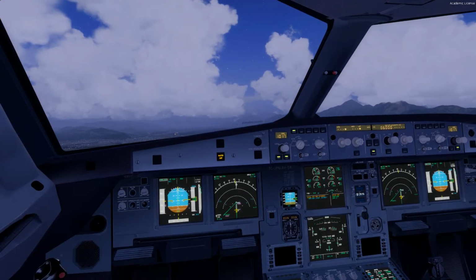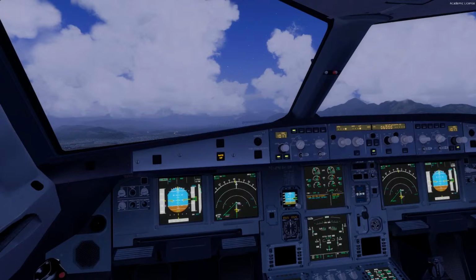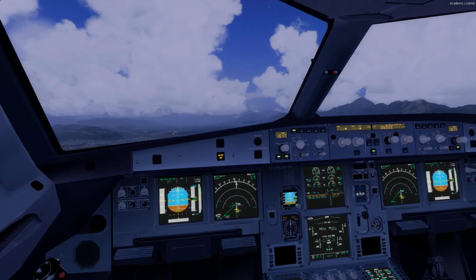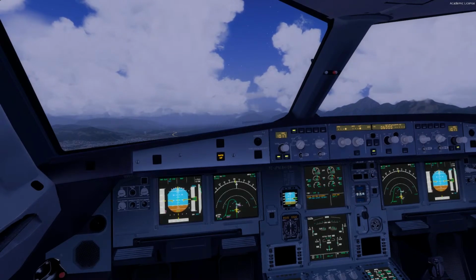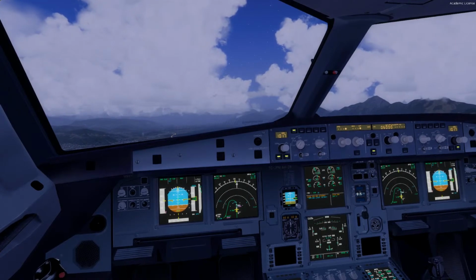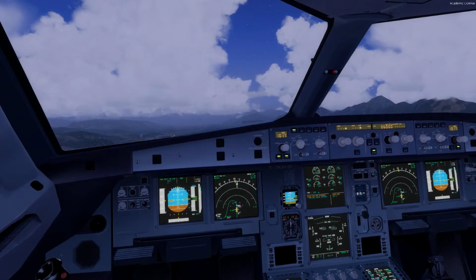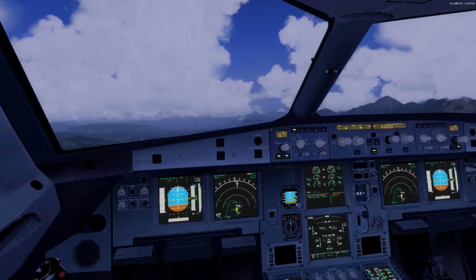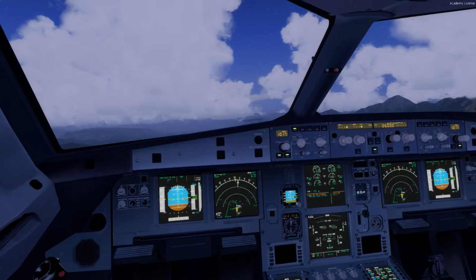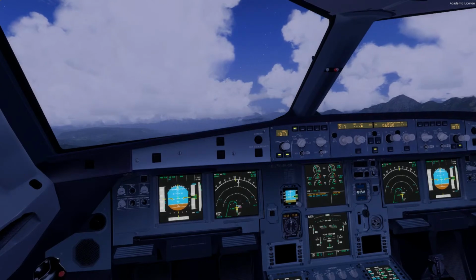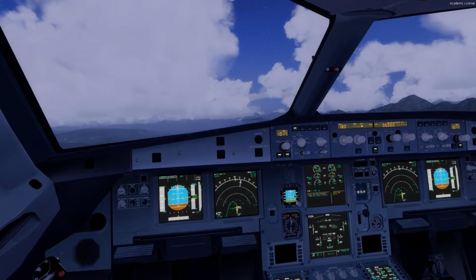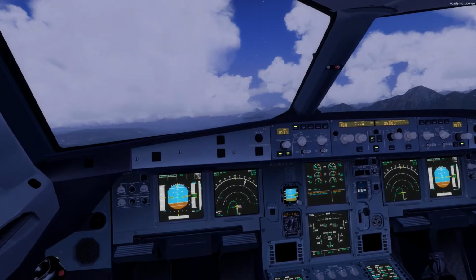So we're continuing to reach 6000 feet, and after reaching Lima Bravo Lima, we'll continue in the left turn. Sierra Bravo Delta, hold position due to arriving traffic. Roger, holding position, Sierra Bravo Delta. And now we'll initiate the left turn for missed approach procedure, and we will have around 180 knots in the turn, and we can also activate the autopilot number 1.